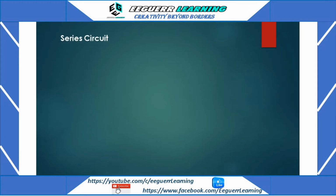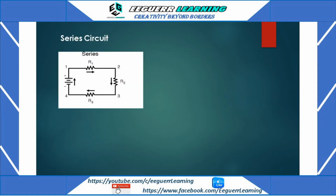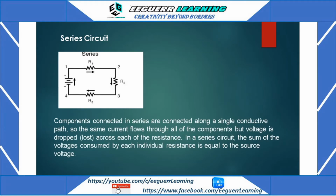So let us check first the series circuit, and let us define what is a series circuit. Components connected in series are connected along a single conductive path. So the same current flows through all of the components, but voltage is dropped or lost across each of the resistances. In a series circuit, the sum of the voltages consumed by each individual resistance is equal to the source voltage.